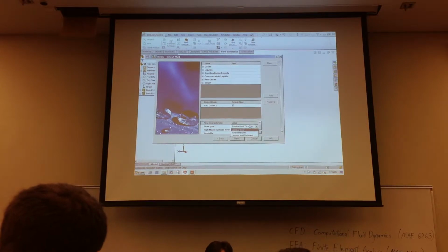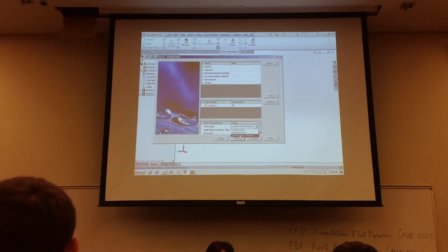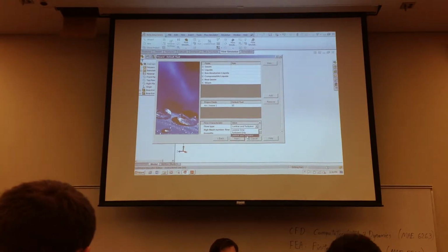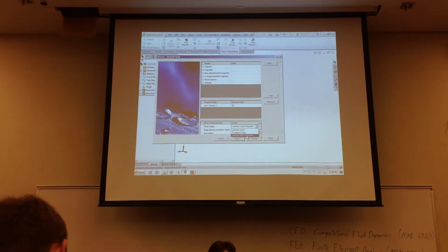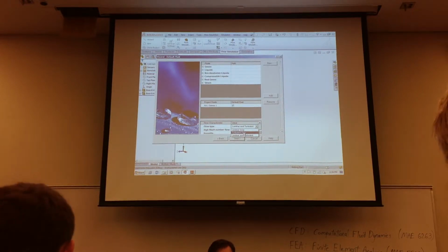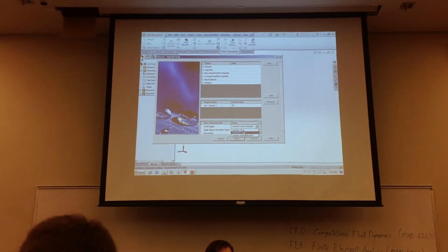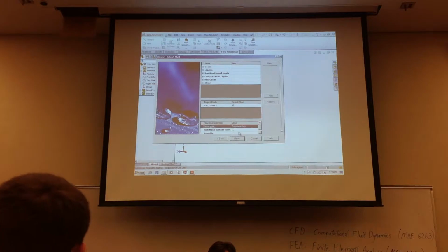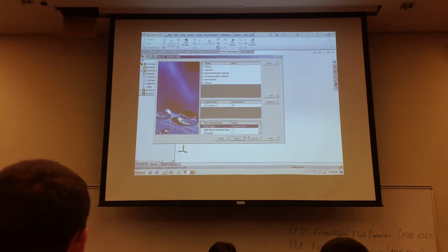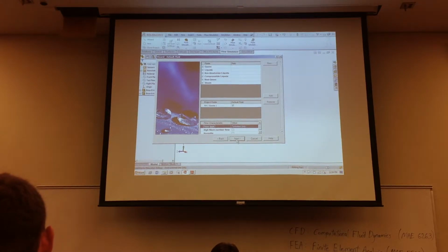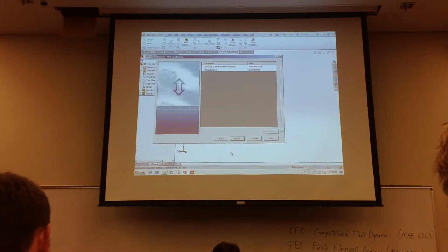In this case, you could choose to analyze laminar and turbulent flow, but the computer would spend a lot of time trying to figure out where that transition actually happens. Now, for simplicity and speed, today I'm going to go ahead and just choose turbulent, because I know the flow behind that sign is going to be turbulent, and I'm not going to worry about the laminar aspect of it at all. So we'll do turbulent only. If you had a high Mach number situation, or you needed to include the effects of humidity, you can turn those on as well.